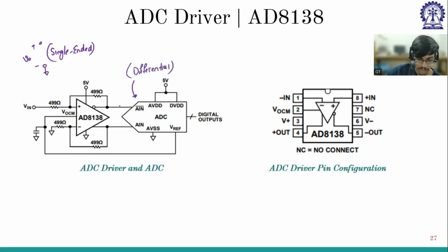So it needs two inputs. So we need a driver such that it will be able to drive this ADC as well as convert our single-ended input to differential. And how are we getting these? These are taken from the datasheet. These pictures are taken from the datasheet. I'll open the datasheet and I'll show you.